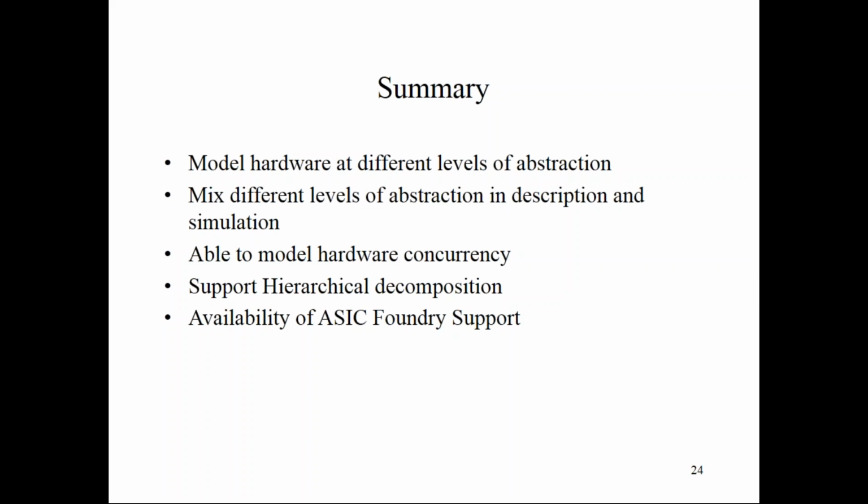Then the ASIC foundry support is also there for describing the Verilog module. For example, if I design any module using a hardware description language like either Verilog or VHDL, then we have to use the technology, that means 180 nanometer or 45 nanometer technology, for the foundry setup.